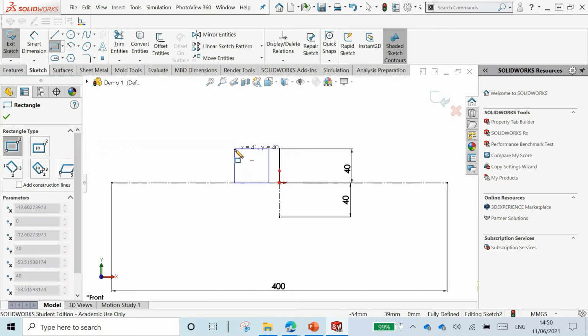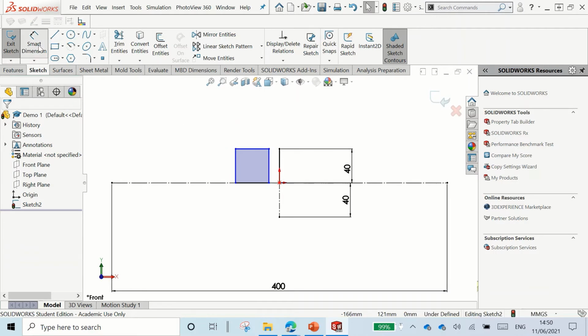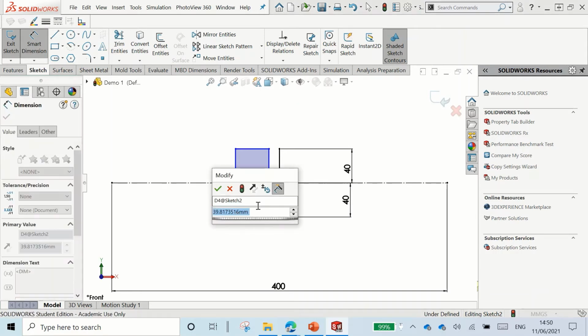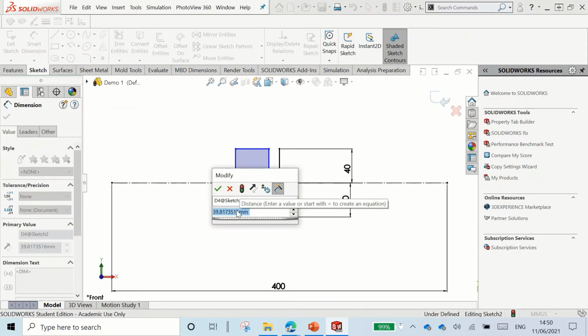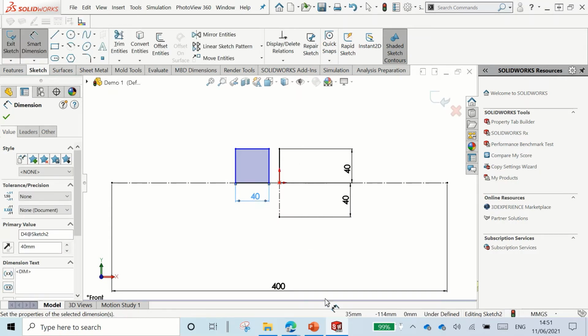So now I'm just going to drag out, and be careful with these, they're just estimates with what's given to you here, rough figures. So when that told me that was 40 by 40, but when I actually go to dimension this out here, so again, click this line, or I can click this bottom line here, it tells me it's 40, but it's actually not exactly 40, which can be important if you're making very precise objects or anything like that. So now I have my square drawn.